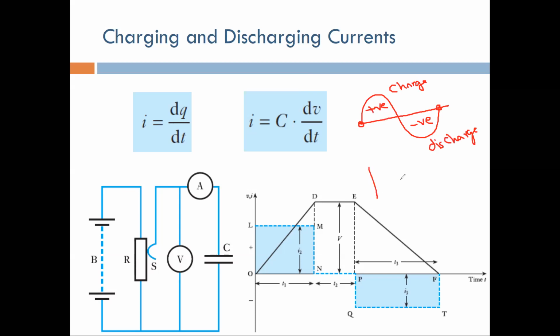This is different from having a current that looks like this, like what we said before. In this cycle you have charge, and here you have discharge, so they cancel each other out. At the end of the cycle, the total gained charge on the capacitor will be exactly 0. What I was talking about before is a constant current: a constant positive value here, a constant negative value here, and a constant 0 here.